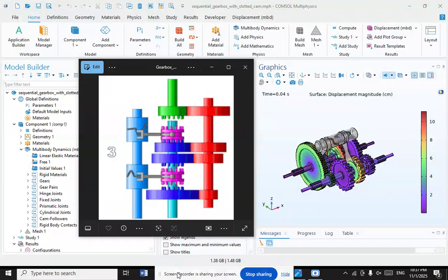When upshifting or downshifting a sequential manual transmission, there is no need to operate the clutch, which is only required when the vehicle starts. Since the engagement ring or dog ring is pushed by the shift fork and moves quickly, and the engagement ring begins to transmit power synchronously while it comes into contact, the sequential manual transmission has the shortest shift speed. The shift time is usually 5 milliseconds or less and is therefore now used in all Formula One cars.